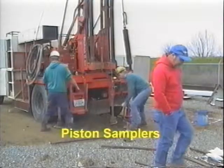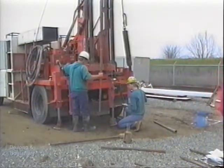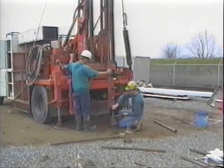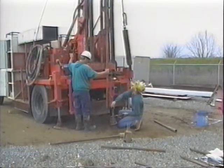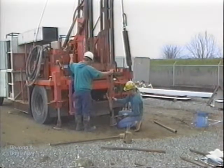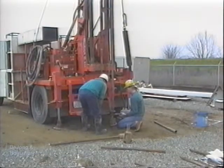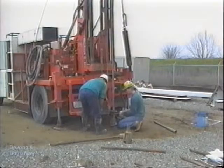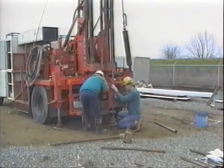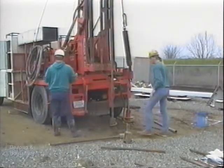Some disturbance to tube samples is caused by the in situ soil being distorted as it is squeezed into the sample tube. When the empty sampler begins its downward thrust, the adhesion and friction on the outside of the tube may cause the soil to rise into the tube faster than the tube is descending. On the other hand, after the tube is partly filled, the adhesion and friction between the tube and the sample oppose the rise of the sample. Under extreme conditions, the initial portion of the sample may act as a plug, capable of displacing soft clay seams or layers so that they do not enter the sampler at all.